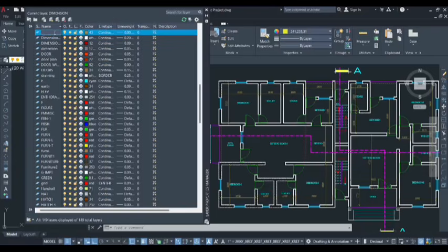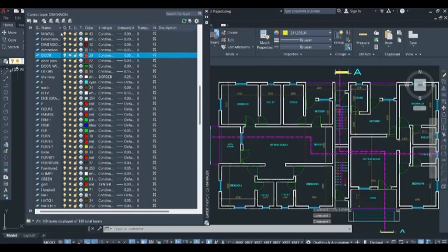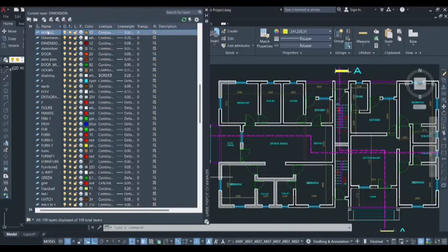So now I'm going to use wall, because I have another wall existing before. To differentiate from other layer properties here, I'm going to use m.wall. That is it. This is the new layer that has been created. Now we've created the wall.